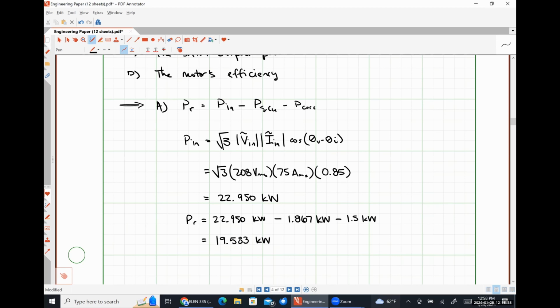Anybody have any questions, comments, or concerns about what we did here? So we're always going to be dealing with line current. Just to be really clear here, if I choose to use the delta connected voltage, I'm going to have square root of 3. If I accidentally use the Y connected voltage, it would just be times 3. We're going to be okay as long as we use the right scaling factor for our three-phase relationship either way. That's the great thing about a balanced three-phase system.